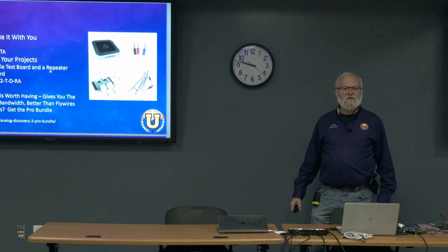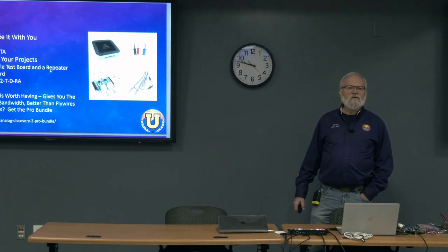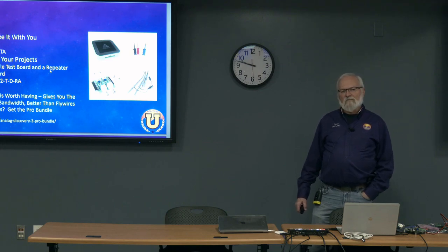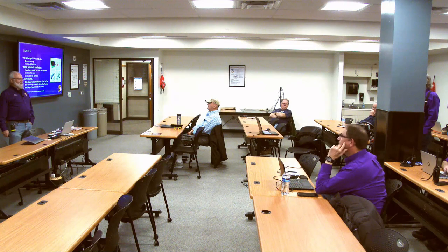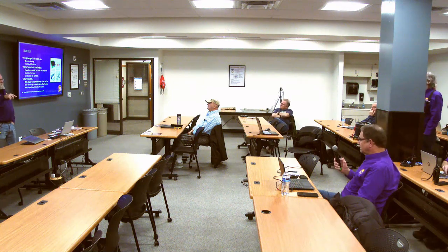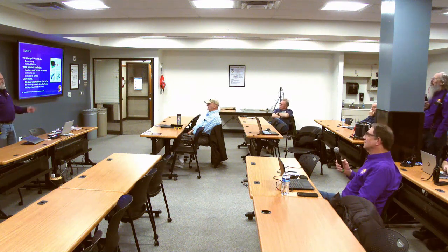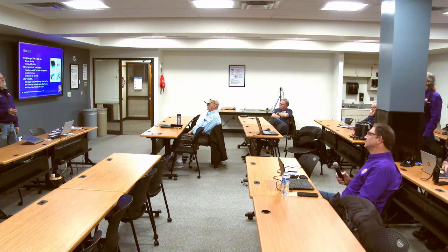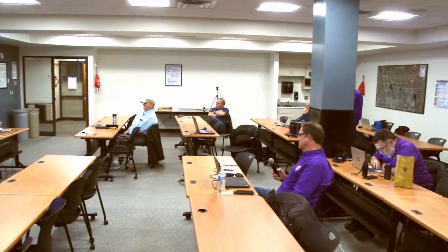Protocol analyzer, is it parasitic, so you can view the protocol that's being generated by another device, or will it actually be the source for generating those signals? Yes. It'll actually do both. You can spy on a protocol that's flying by, or you can be the master. And you could drive the transaction.